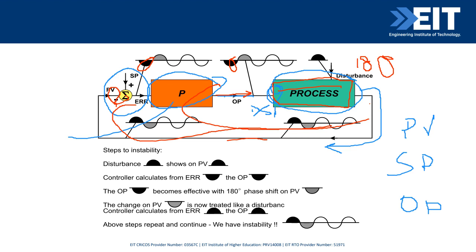And it is because a temperature loop has a lot of lag in it. So when you have PI control on its own with a temperature loop, you're adding a lot of extra lag in, and you could push your loop towards instability. By putting in derivative control, the 90-degree lead cancels out the 90-degree lag.